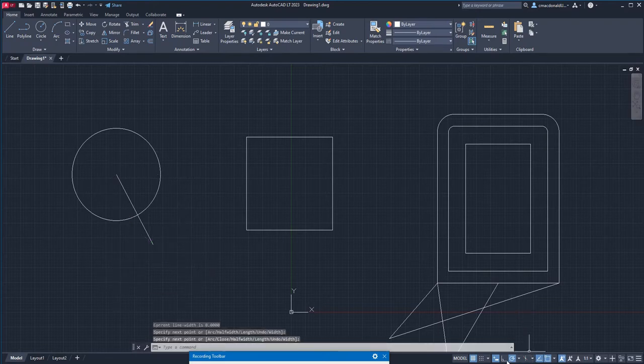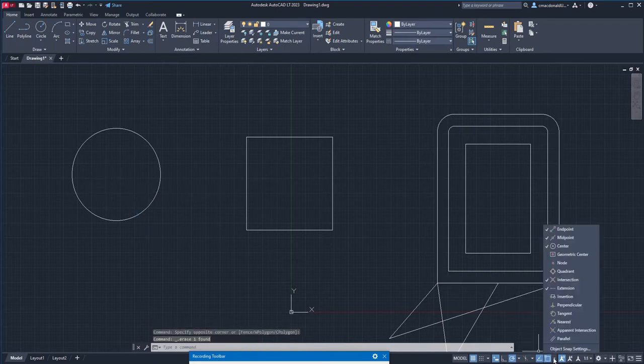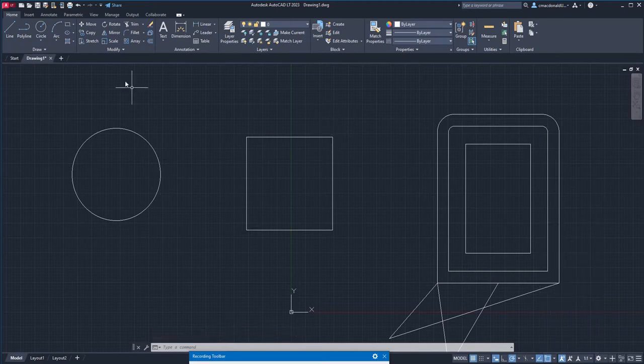Now naturally, if I turn it off, here, I'll turn this off. We'll delete that really quickly. Watch what happens when I turn it off. I'll left click, I will uncheck center snap, and now when I try to draw a polyline, look at this, it's completely random. I can get pretty close, but it won't be exactly at the center of the shape.